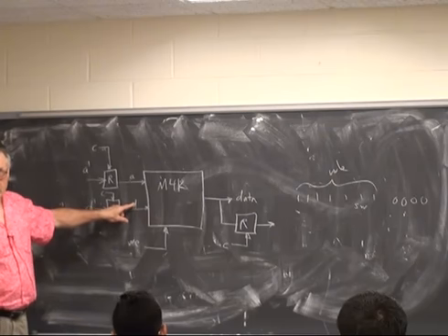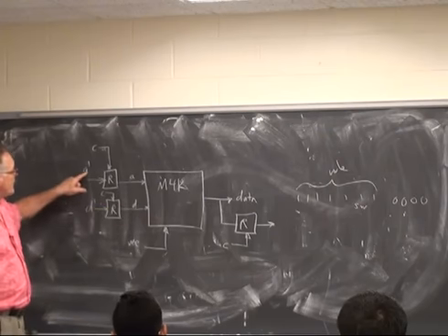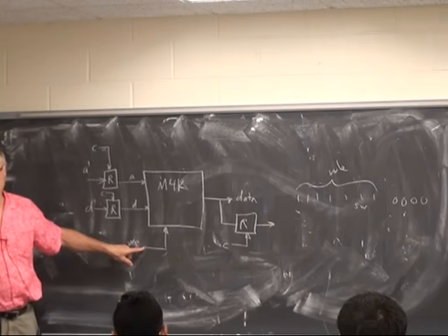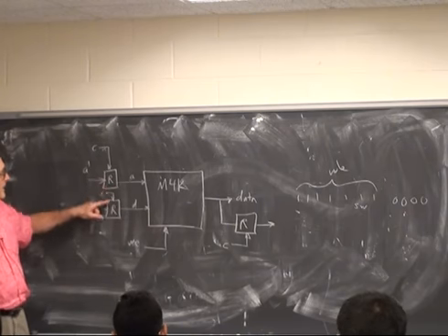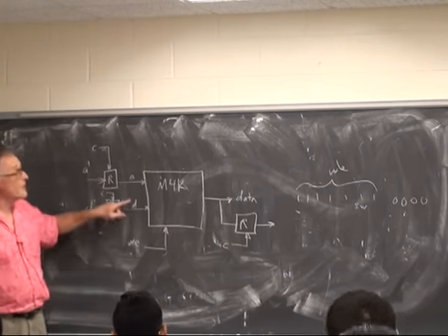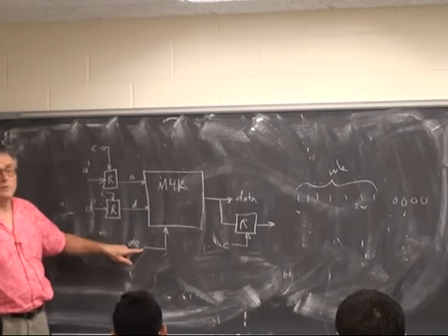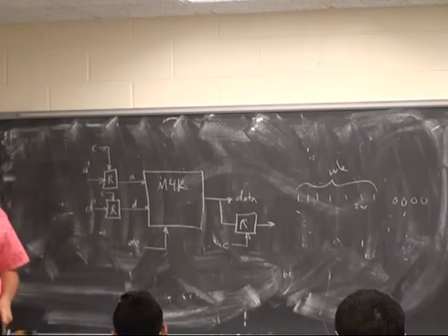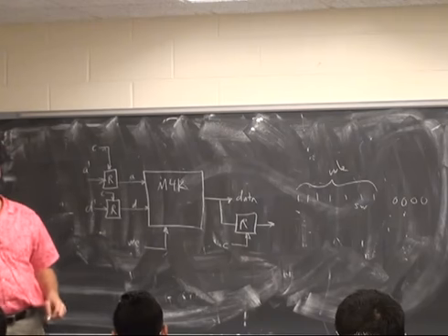That means in a clock system that you have to load the address prime and the data prime 1 cycle before you raise the write enable. So the data and address have to be stable for 1 cycle so that they're on these buses before you raise the write enable. Otherwise, you will write some other address than you think.